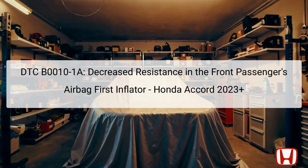The Supplemental Restraint System, SRS, monitors all components associated with airbag functionality, including wiring and circuit integrity. If the SRS detects a voltage level on the detection line that falls below a specified threshold, it considers this a malfunction, which then leads to the storage of this code in its memory. It is crucial to address this issue promptly, as it directly impacts passenger safety in the event of a collision. This guide will outline the necessary steps to troubleshoot and rectify the underlying problems related to this DTC.